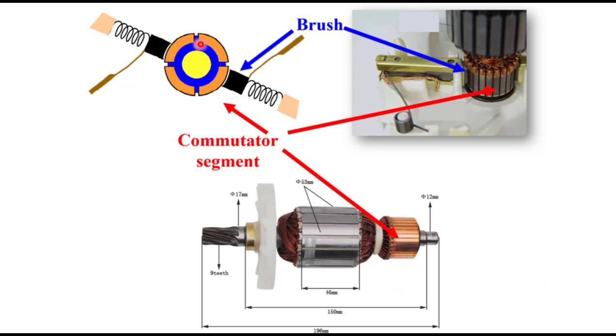Now, our example shows only 4 segments, but in reality, we're going to have many because here are those windings. Here's the steel, the laminated steel that these windings are wrapped around, and you can see that there's quite a few windings, and each winding or set of windings, because sometimes we parallel windings, are going to be attached to these commutator segments to receive and pass current to the real world.